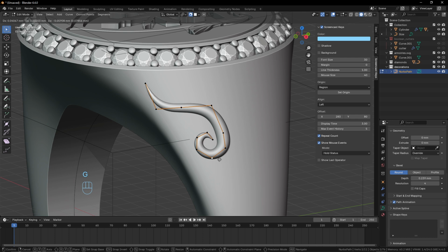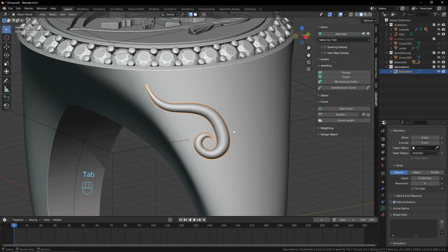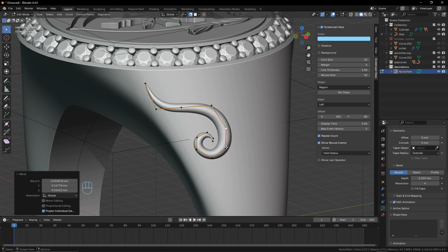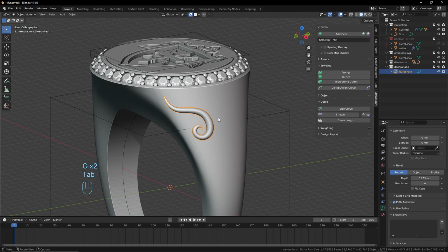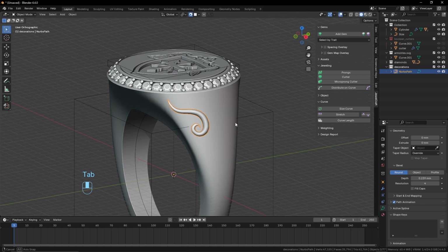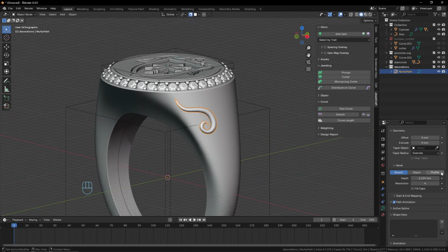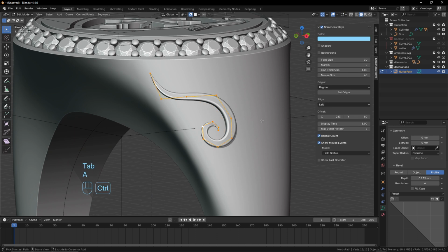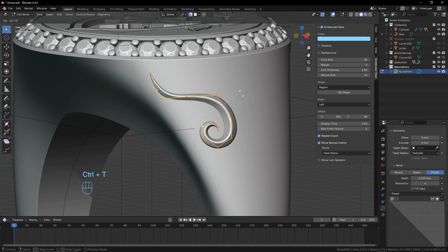Maybe sometimes you have to readjust a little the entire shape like that. Okay, so depends of your need, and maybe that one as well has to be realigned. So don't hesitate to just spend a little of time until you have the right shape. The first one is the most important. You can play with profile, for example, and in that case, you will certainly have to make a readjustment. Like for example, here I can make Control T to realign the curve like this.